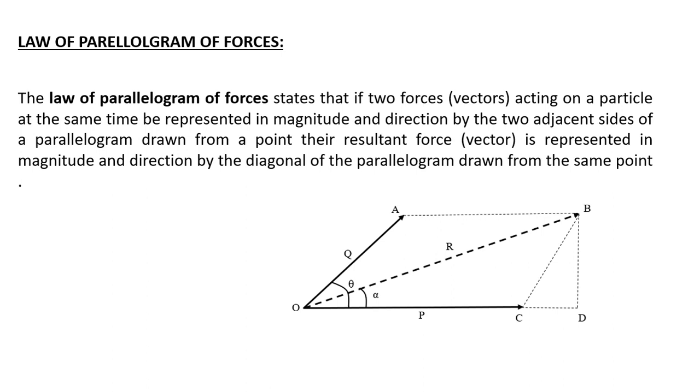Next is the law of parallelogram of forces. The law of parallelogram of forces states that if two forces acting on a particle at the same time are represented in magnitude and direction by the two adjacent sides of a parallelogram drawn from a point, their resultant force is represented in magnitude and direction by the diagonal of the parallelogram drawn from the same point.